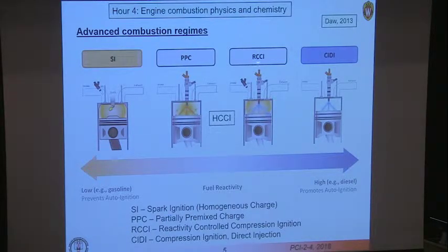And the other idea that we'll be talking about later is what we call reactivity-controlled compression ignition, where we introduce gasoline into the intake stream, and then we introduce diesel fuel direct injected into the combustion chamber. So now we have the benefits of not just the low tendency towards auto-ignition of the gasoline, but the high tendency towards auto-ignition of the diesel. And in that way, we can control the combustion process, as I'll discuss with you later. So these are what are called advanced combustion regimes. There are, of course, other concepts, but these are shown here just to point out that fuel reactivity is extremely